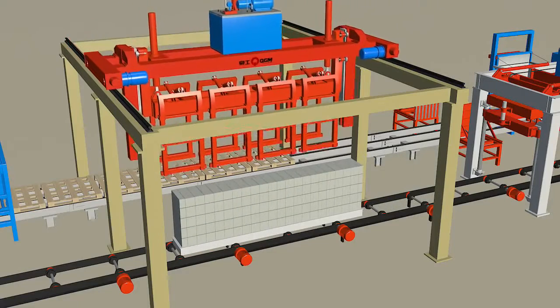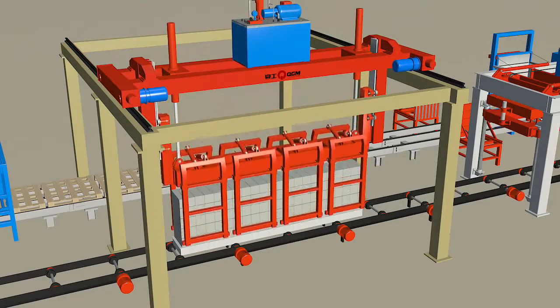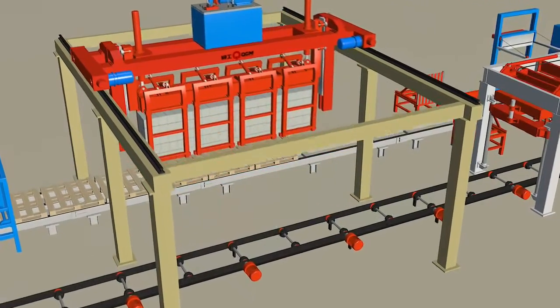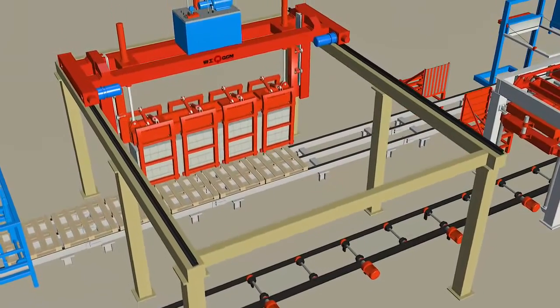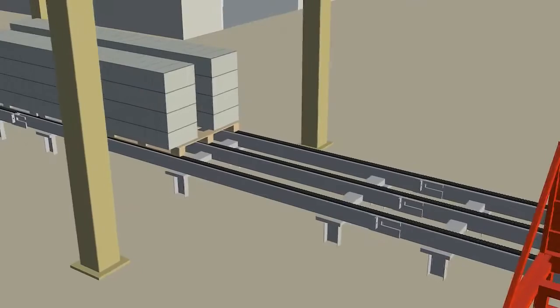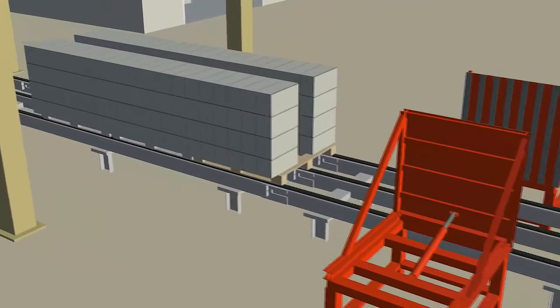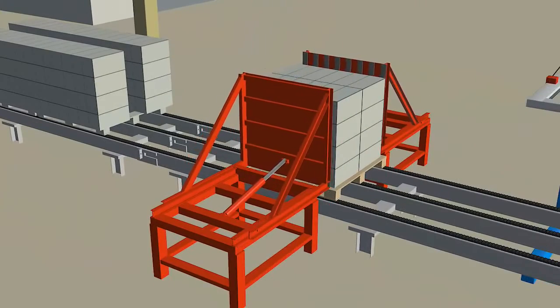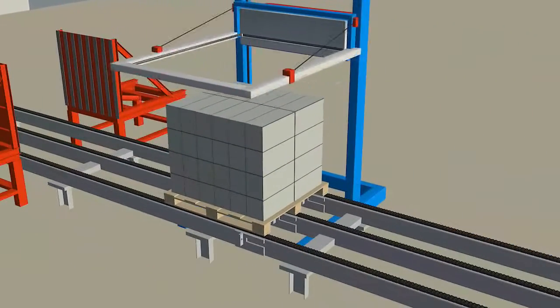The separated blocks with the side plate will go to the crane of the finished products. The jig clips up the blocks and transports them to the wooden pallets on the chain conveyor. Then, it comes to the packing procedure. AAC can be packed manually or automatically.